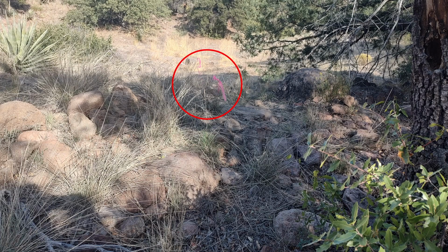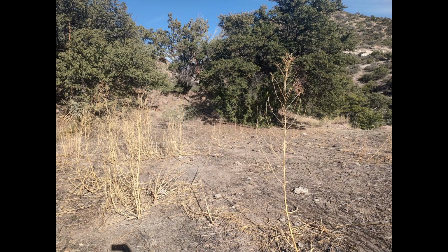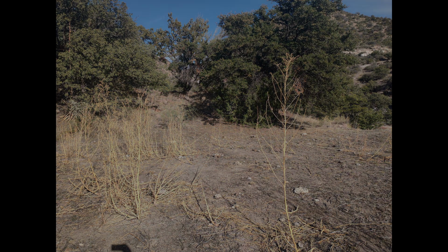The flags were placed to mark the center of the spillway to build. The spillway would be built so that water would flow in a wide path at one elevation, so no rock would be needed to control erosion. The spillway would be dug so that it's level along its length and there will be no erosion. The entrance and the exit of the spillway would be at the same elevation.